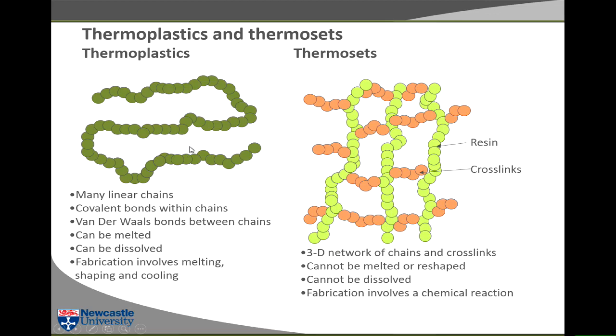And you can see just the way I've drawn this chain here. If you've got many of those together in a solid state and you apply a stress to it, the thing that you're mainly loading is the bonds between the chains, not the bonds within the chains. And the bonds between the chains are the weak bonds. You can actually make these polymers very strong. If you stretch all these chains out and line them all up, which is not easy to do, but if you do that, then you can make things like Kevlar, which is very strong. It's stronger than aluminium or steel. Make bulletproof vests out of it. You can do the same thing with polythene, actually. It's called Spectra, but we don't use that in pipes.